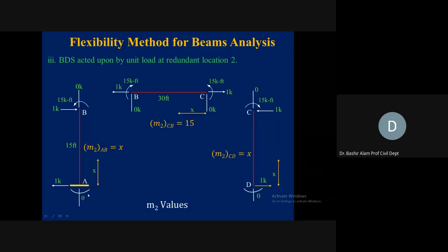Now, starting from A, we put AB in equilibrium. So 0 upward, so 0 here also at B, in the Y direction. Summation of Fy is satisfied. 1 kip is leftward directed, so 1 kip in the rightward direction. So summation of Fx is satisfied.